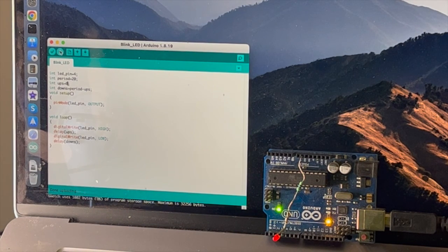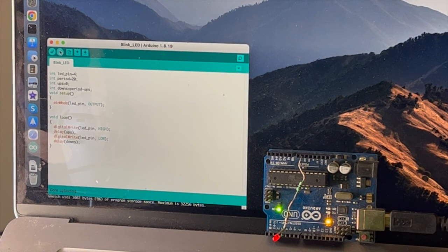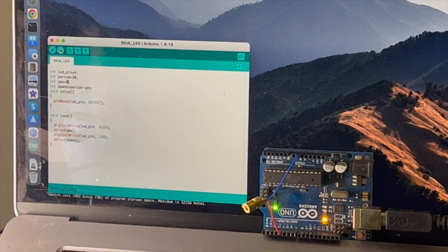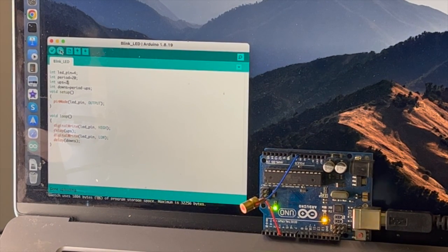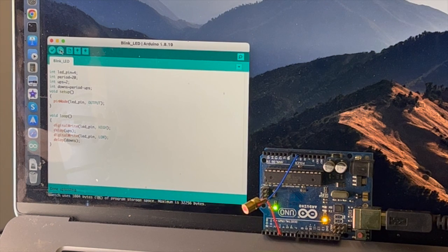This is how you can change the brightness of an LED using pulse width modulation. We can replace this LED with motors, which can speed up or slow down as you want by changing the duty cycle, or a laser diode, and you can control the intensity using the same idea, and we can control a lot of things. It's a powerful technique. We will apply it for various fun aspects with the Arduino pulse width modulation.